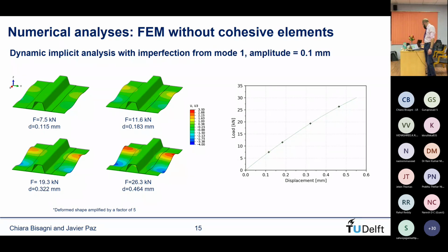And then for the next one, to see how different the specimen would behave if it developed another buckling mode, what we applied is the imperfection from mode 1, which was with 2 half waves per side, but the symmetric configuration. And we see that the response is virtually similar, except for the buckling shape. The first displacement response is very similar to what we got from the other.